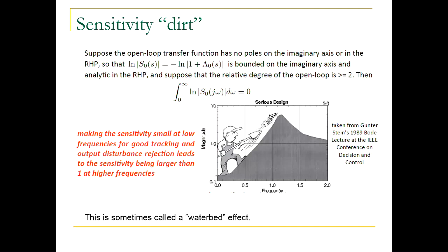So you can see just from that fact that unstable open loop poles would make your design harder. If you have an unstable plant, the open loop transfer function inherits those unstable poles, right? We will not be canceling the unstable poles of the plant directly with the controller. We talked about why not before, but unstable plant poles result in a positive integral, and that means the design is even harder.